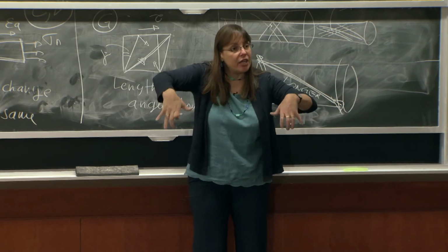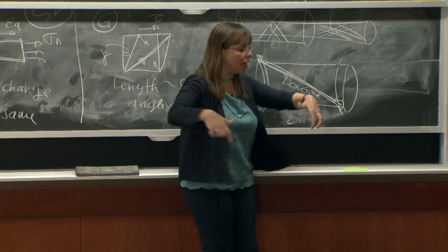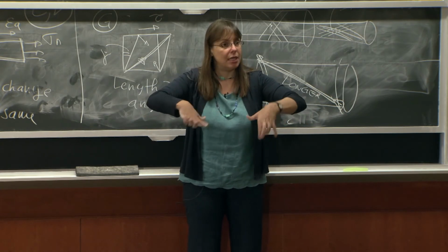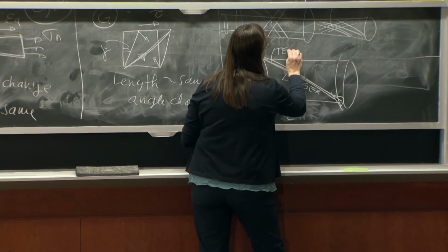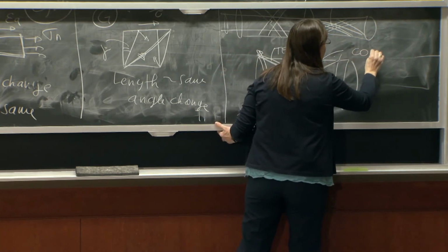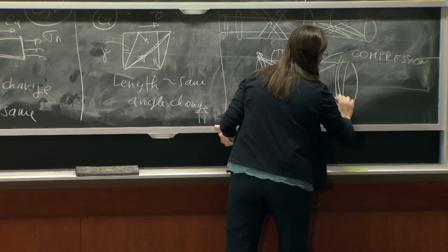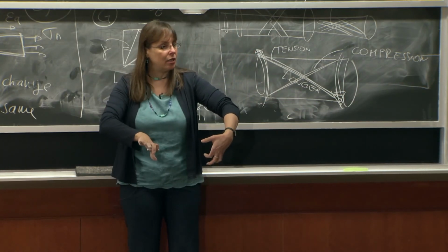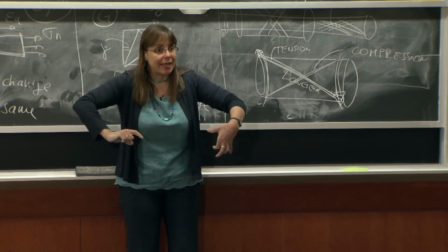I get farther away on that diagonal. Instead, these two that were a certain distance apart, when I rotate it, they get together. So along this line, I have tension. Along this line, I have compression. And that is why when I twist the soda can, it buckles at 45 degrees on the diagonals that get in compression.